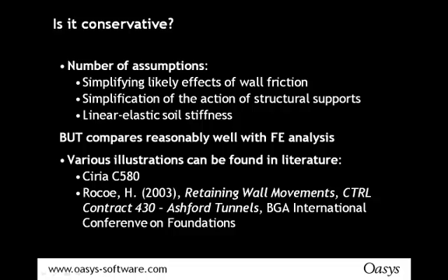The initial stages in ground often exhibit higher stiffnesses, but this isn't represented because of the linear elastic soil stiffnesses. It is, however, very difficult to give an estimate of the amount of overprediction, and this is because with each individual problem there's a variability in site and local conditions. So we couldn't maybe put a value on it as such. And in order to look at this, we and Arup and our external customers have done numerous studies, and there's a lot of literature out there to show how it compares.